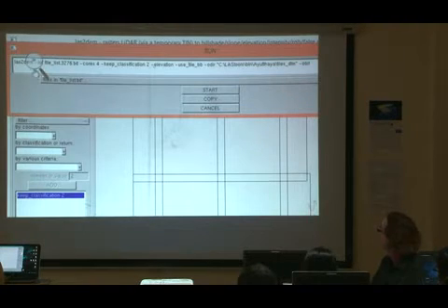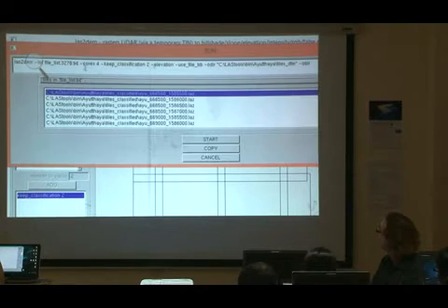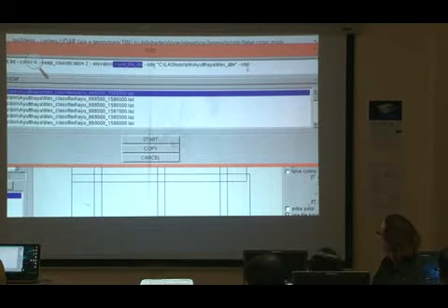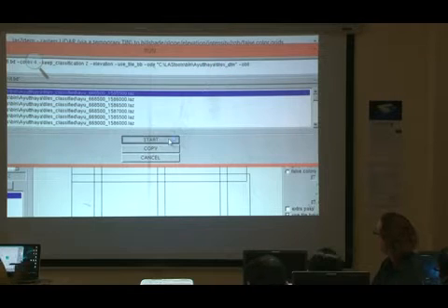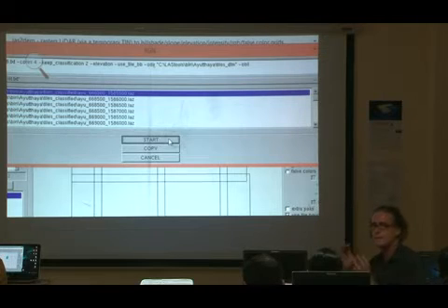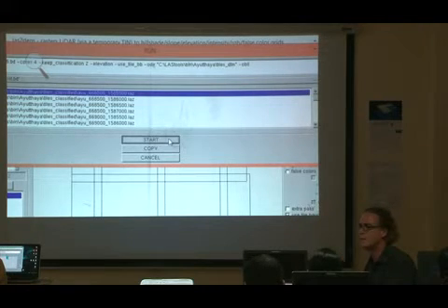Running. Last step. For the course, I keep the ground points, I raster the elevation, and I only use the tile bounding box. And I put all these tiles into the tiles DTM directory, in build format. And now I should get 16 DTM tiles with 1 meter resolution that fit perfectly together.